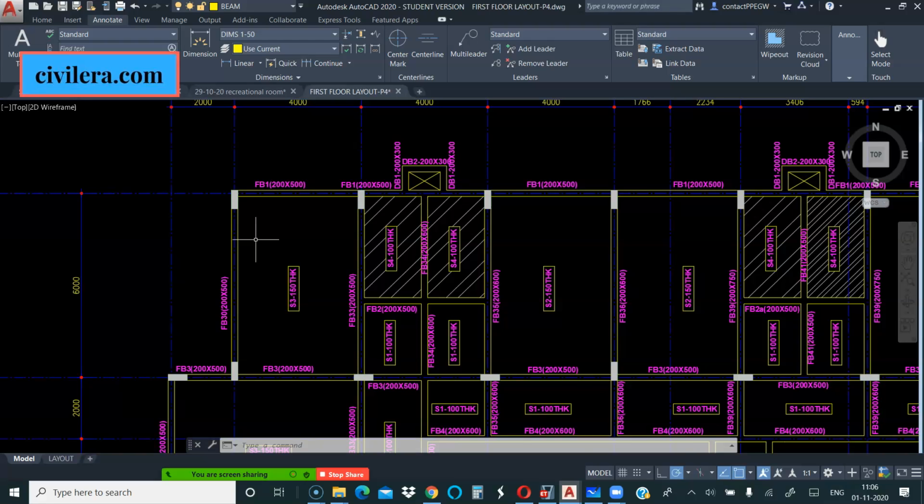But as long as your column has say 2 to 3% of steel and you have taken care looking at the efficiency, then there is no point in saying that less number of columns are going to be better. Nothing like that. Structurally your cost is not going to increase simply because the number of columns is more. If you need that many columns, that is the right number and that will be the right economy. So I would say don't reduce the spacing to something like 2 meter, 1.5 meter.